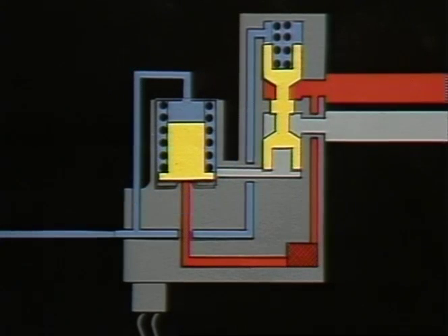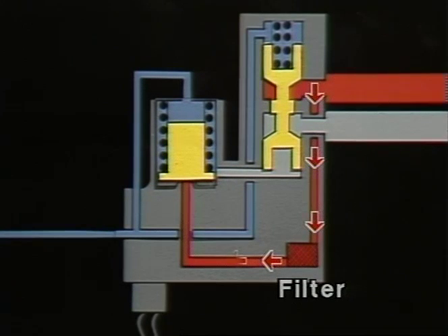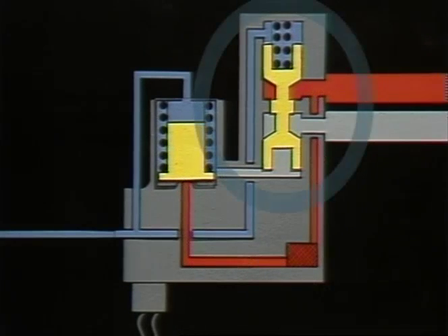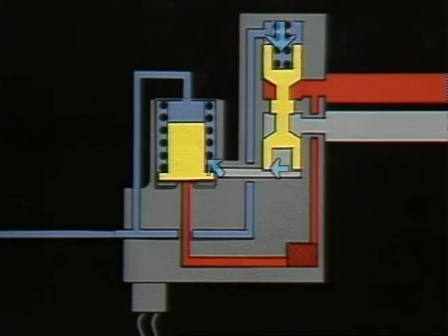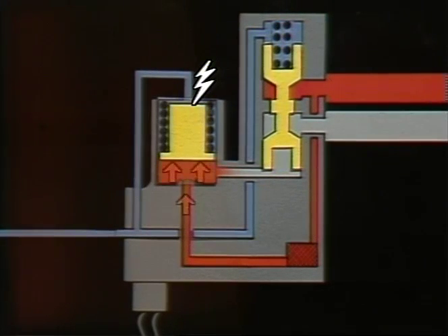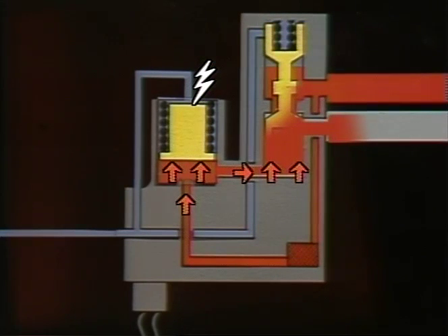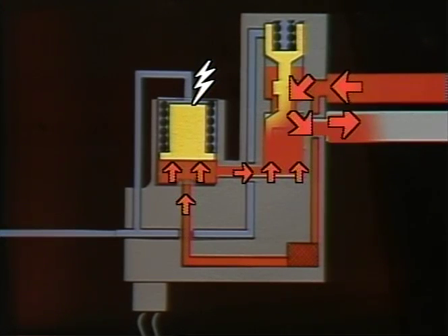In this condition, pilot gas, tapped off the main inlet supply, is internally filtered and trapped by the de-energized solenoid core. The main spool is held in the closed position by a spring, while the other end of the spool is allowed to vent through the pilot solenoid valve. When the solenoid is actuated, the core is magnetically raised and allows the pilot pressure to shuttle the main spool valve by overcoming the spring tension and venting that area. This spool position now allows the main supply gas to pass on to the lubricator.